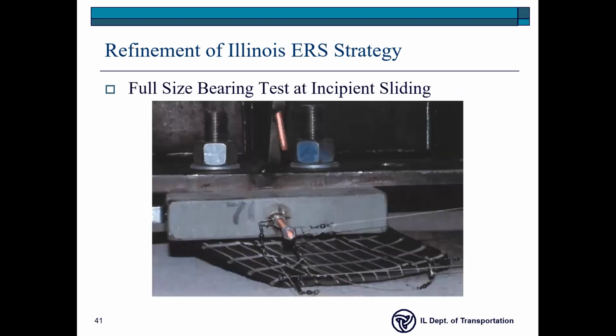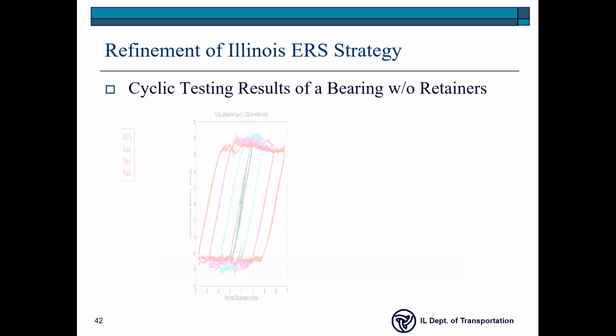And so with that particular apparatus, these are the first tests we were running. We were really pushing these rubber bearings way past their conventional design limits for regular loads that were not earthquake loads. And to our knowledge, we think that these were the first tests on bearings like this, pushing them this far, that have probably ever been done in the world. If they weren't the first, they were one of the first. Okay, so this is very, very interesting testing.